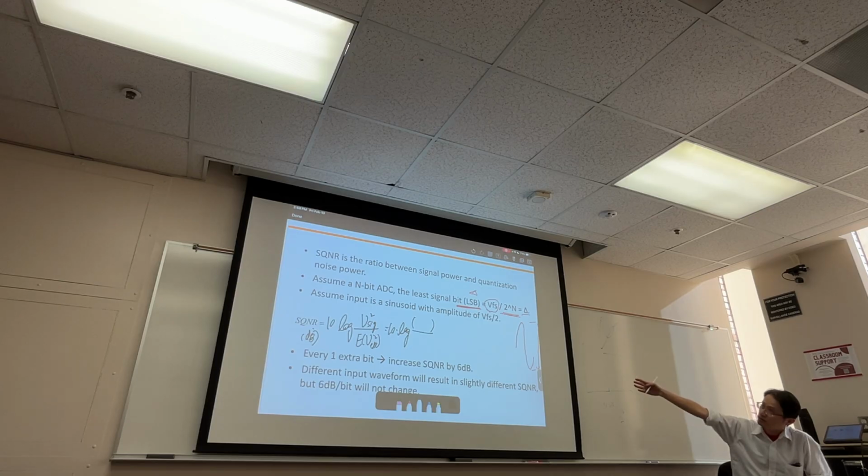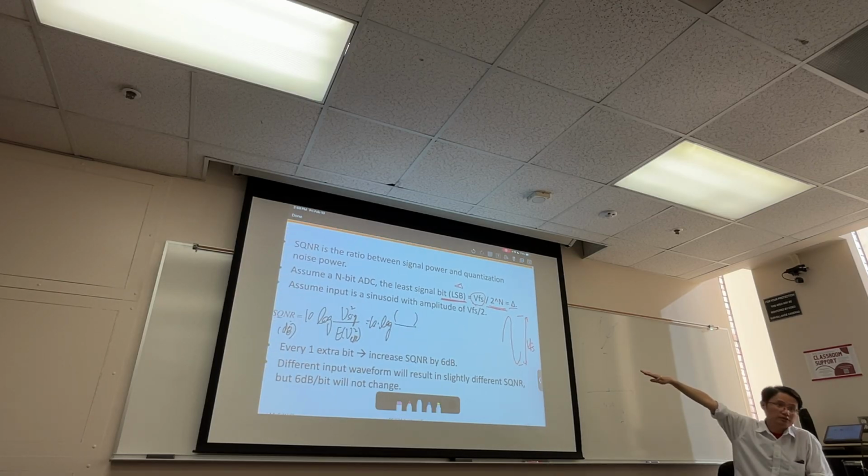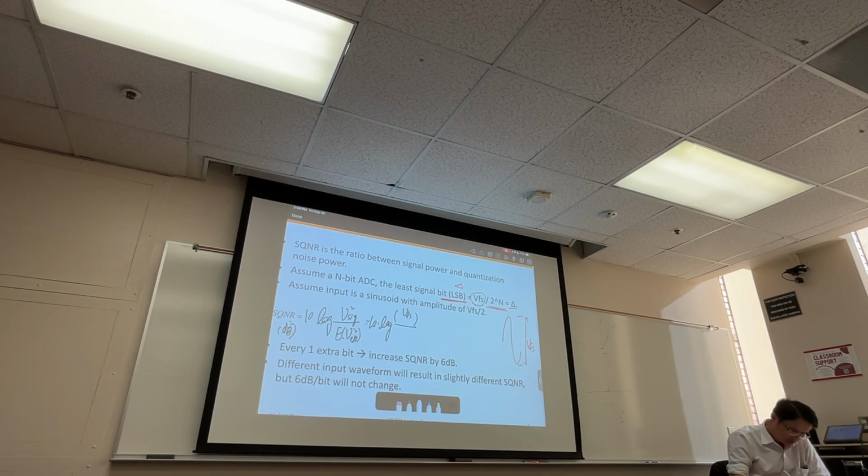Amplitude, so what is amplitude? What's the amplitude of this sine wave? I know my drawing is not very good, but imagine half of that, right? So VFS over 2, squared, divided by 2, right? That's the signal power.